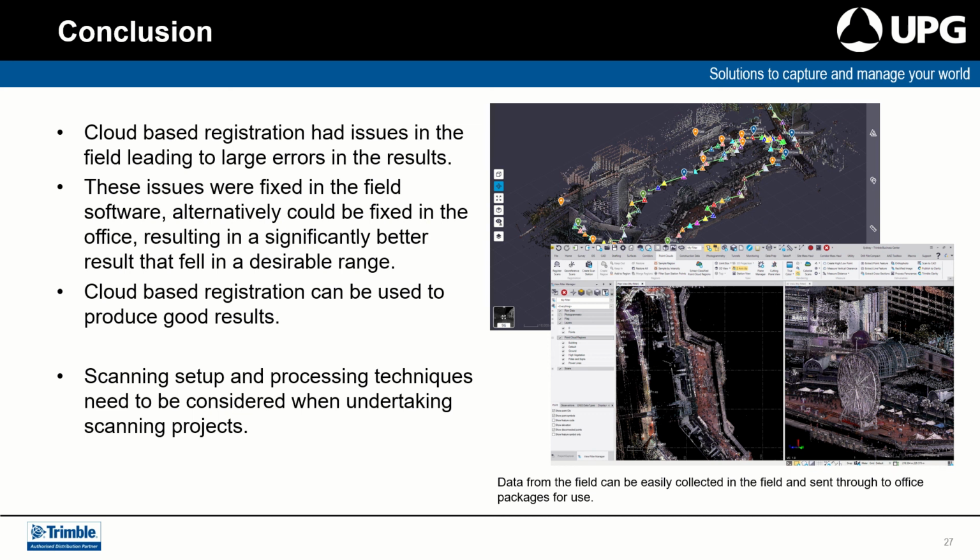Cloud-based registration was a good tool to be using in this particular project, and it did produce very good results. The scanning setup process and techniques need to be considered when undertaking large scanning processes, and it's always worth noting that when errors do occur, it's worth going back through and looking through each of the individual setups and the reports that come out to make sure you can see where errors are accumulating and what is going on within a project.